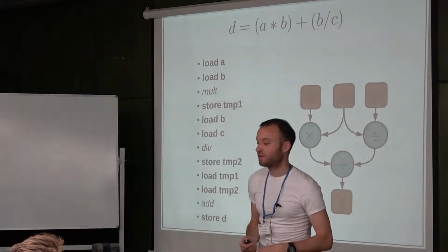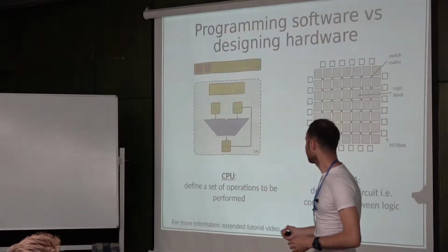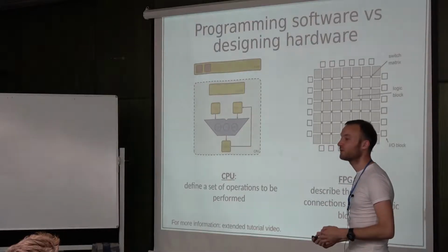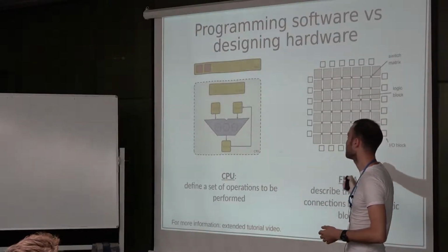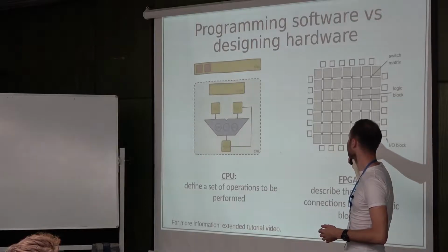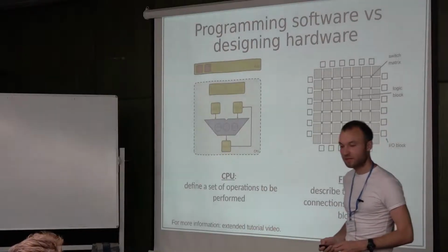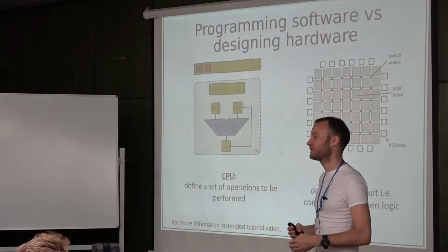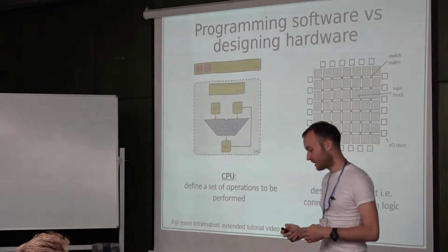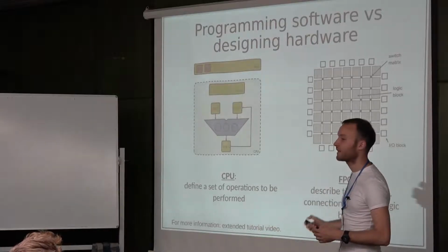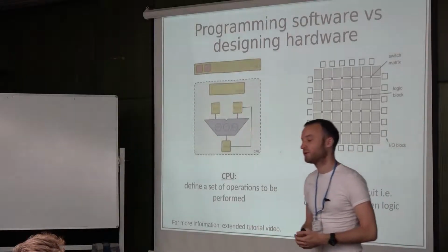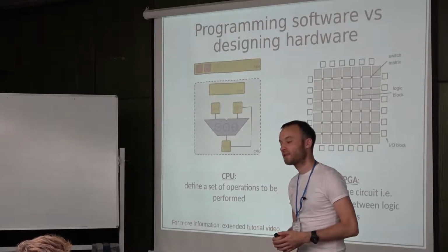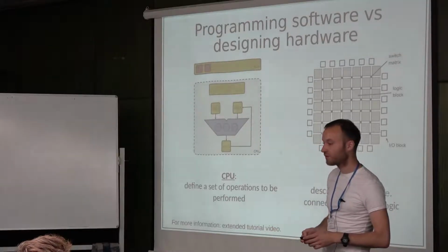Yeah, and now the question is, okay, we know that we are flexible, but how do we exploit this flexibility? So how do we configure these switch matrices, these tiny matrices? The main designer's goal is to figure out what is that bit stream that describes connections within that switch matrices. But obviously we will not do this on bit level. So we will use some higher level languages that allow us configuring these matrices.